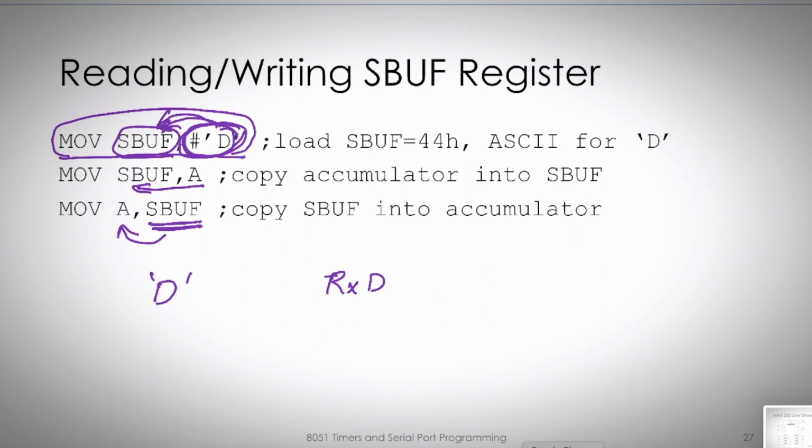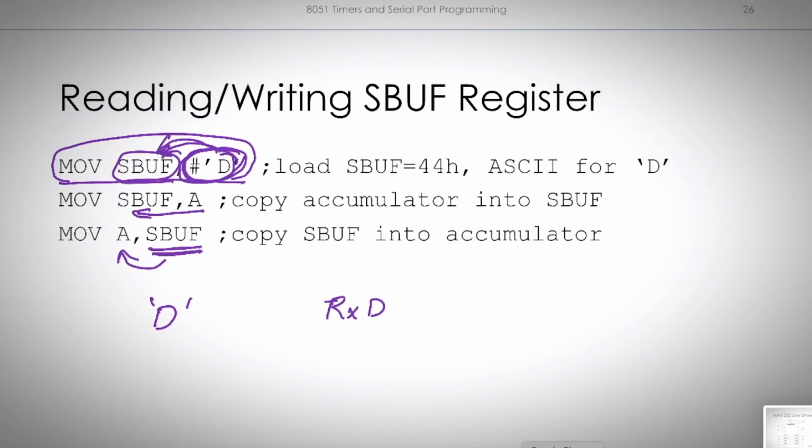We don't have a separate SBUF register for transmission and a separate SBUF register for receiver. We have only one SBUF register, and internally the microcontroller will take care of whether it is a received data or whether it is data to be transmitted. This is the idea.